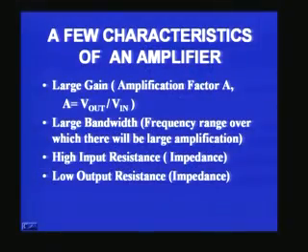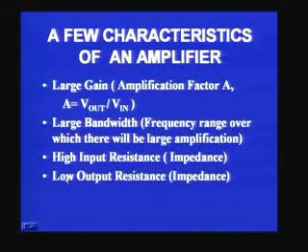Apart from these two, the amplifier should also have high input resistance. It is more pertinent to call that impedance because it can be complex. It will have both real and imaginary parts, and therefore for simplicity I am saying it should have high input resistance, and it should also have low output resistance.